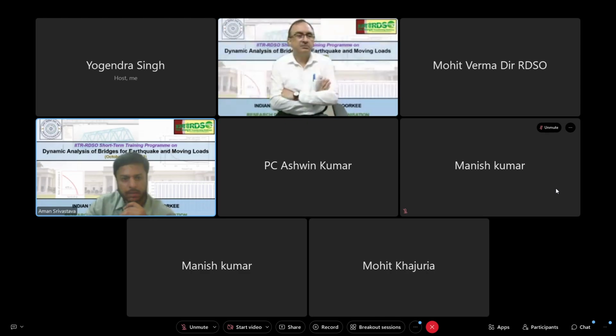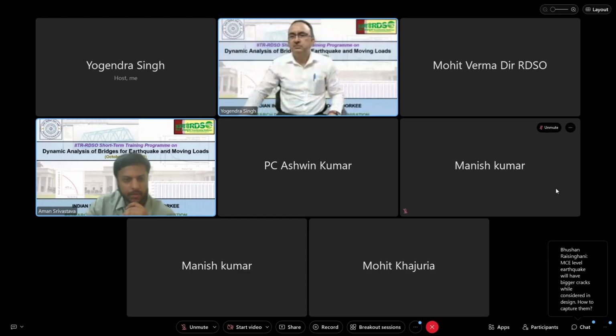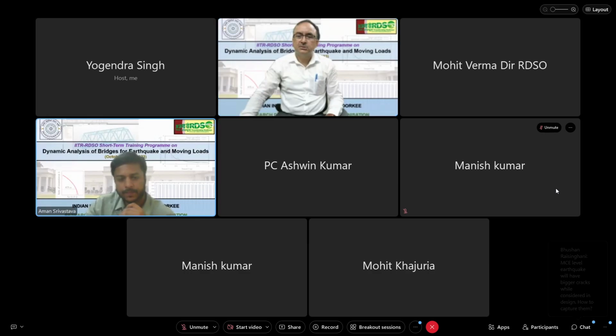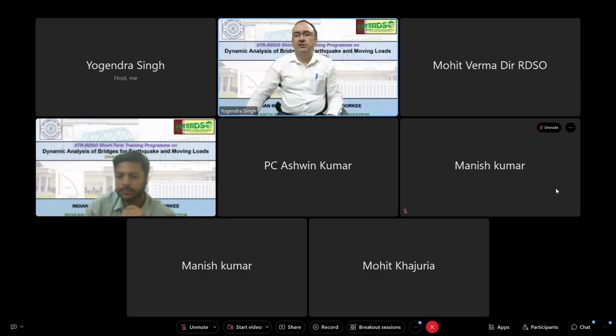Then we have a question from Mr. Jay only. What is the difference between equivalent LRSM and ERSM? Okay, so ERSM is conducted for elastic structure. Equivalent LRSM is done for nonlinear structure, but by iteratively performing a number of elastic analyses.